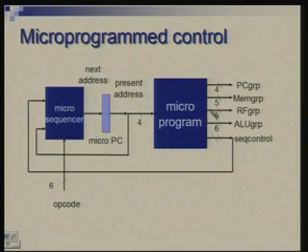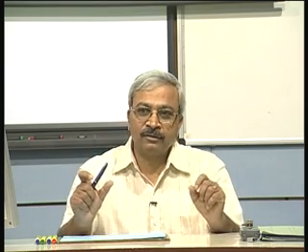we think of a memory here containing the microprogram, and all we are doing is reading out words of this memory. Okay. So you might think that now I am again talking of memory, although I have just mentioned some disadvantage of a memory based design, but there are differences you will notice. So imagine a memory which contains a microprogram. What this microprogram is, is nothing but each word contains a bit pattern which needs to be applied as control signals to the data path. Okay.